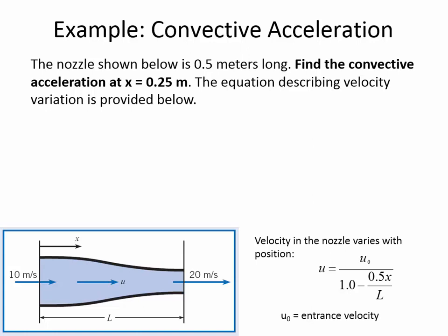And so right here at the end of the nozzle, it seems like the diameter is basically parallel again. And so there's no more acceleration happening here because the shape of the nozzle has stopped changing. So there's no acceleration there. And there's no acceleration here because it hasn't yet started changing. But in the middle, those two walls are coming closer together, it seems like at a pretty rapid rate.